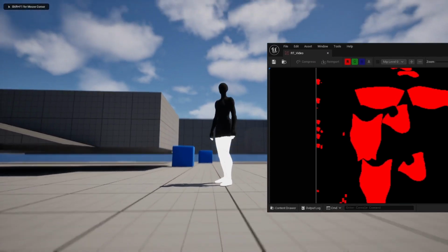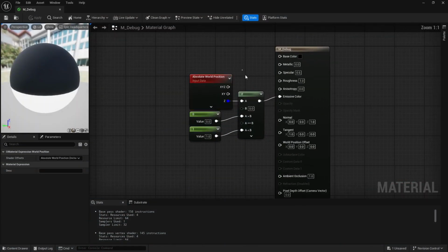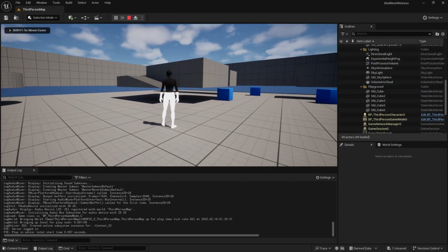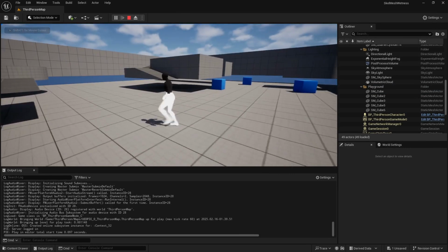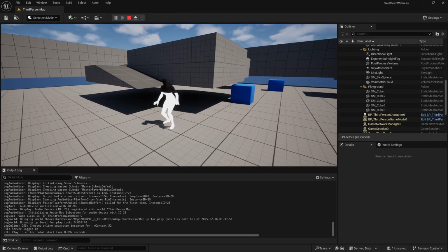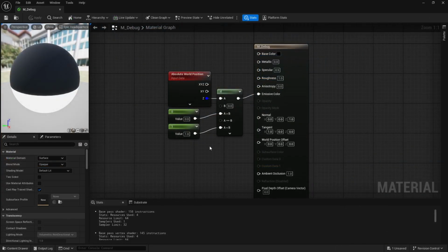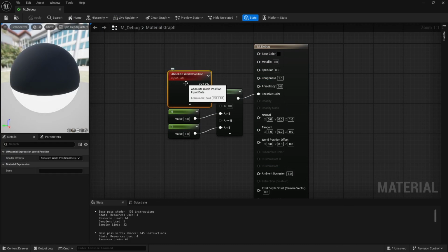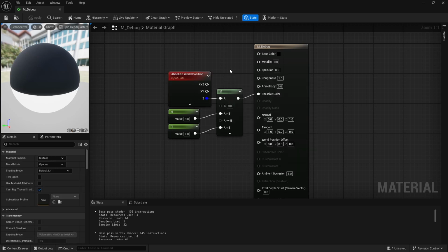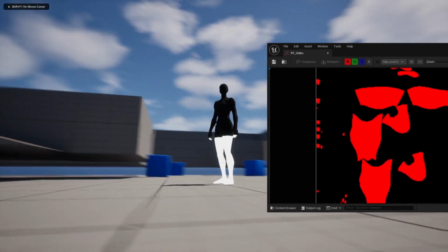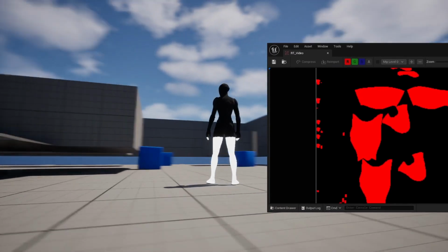At this point, you might say, well, just use a material on that skeletal mesh, sample the world Z, and create a mask. Simple. Well, yes, but you'd be missing the point. To create a persistent effect, like I'll discuss in a minute, this mask needs to be drawn into a render target for us to be able to fetch it the next frame. And when drawing into a render target, guess what? This corresponds to the render target's pixel coordinates. This absolute world position, actually reconstructed from the depth, only exists when rendering the scene, not when rendering into a render target, if that makes sense. And that's why to create such persistent effects, you have to go through more complex setups like the one I'm demonstrating.